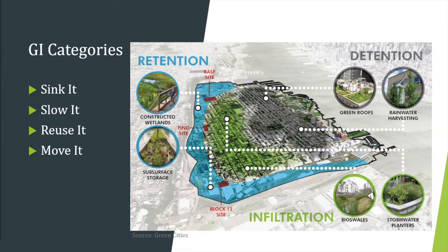What about the theoretical and practical? Like any mechanics involved in here? Yeah, so technically what is the green infrastructure element capable of? So you can look at something and say, all right, and I'll get into this a little bit. If I'm going to have a bioswale, I know that I need to be this far off the water level, I need this much space, I need this much infiltration sand. Like there's the design in the theoretical state.